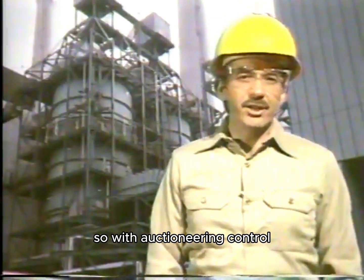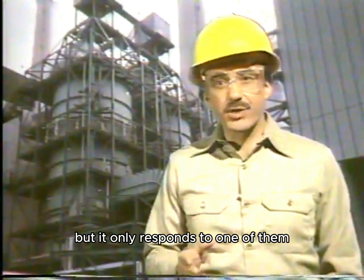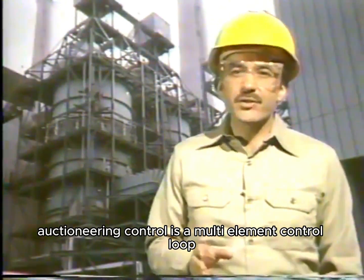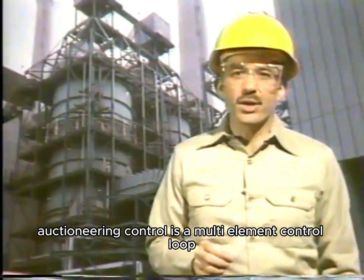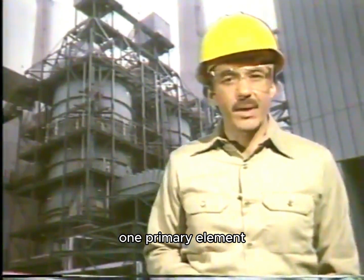So with auctioneering control, a controller measures 2 or more input signals, but it only responds to one of them. Auctioneering control is a multi-element control loop because the controller receives an input signal from more than one primary element.